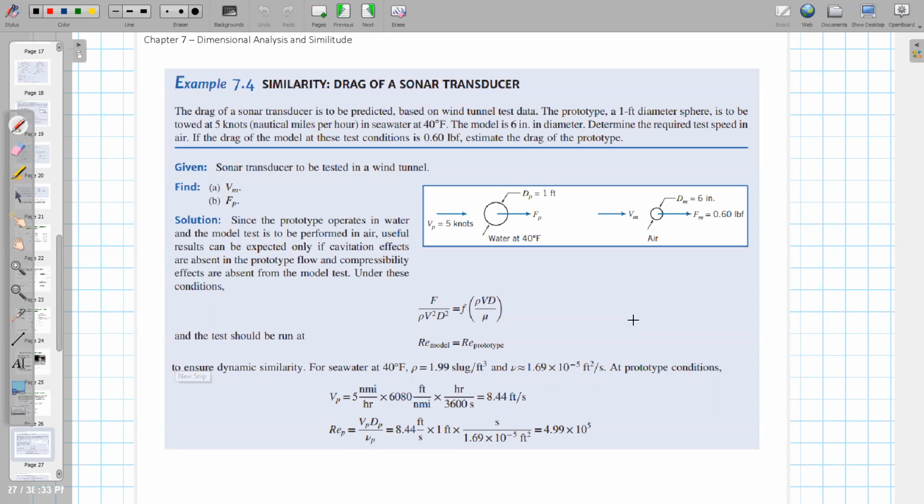By doing this Buckingham Pi theorem, when you find the dimensionless parameters, you know which one is important and which one is not important for your problem. Then you can design your experimental study, actually design your experimental model, so that the model does not need to be as big as the realistic one.